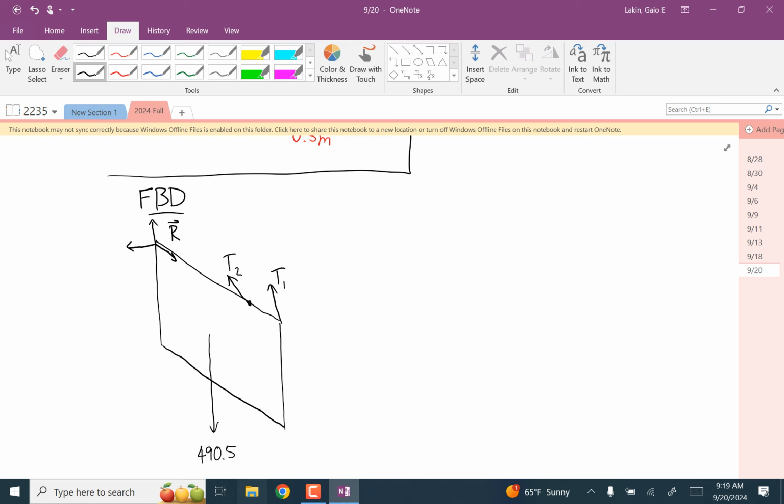With 3-dimensional problems, pretty often it'll come out that one or more of these equations are just going to come out to be trivial equations, 0 equals 0. That's what's going to happen here. So the fact that we have 5 instead of 6 isn't usually a problem, but you never know for sure until you see what the equations look like. Any questions about that free body diagram?